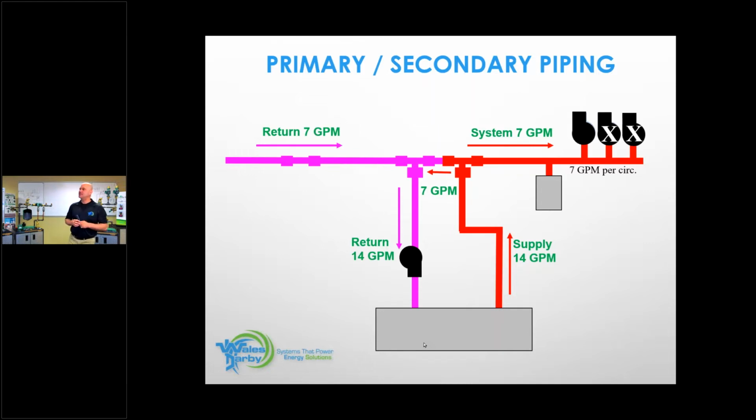What do you got? We got the capacity's gonna ramp down. Okay, great answer. Why will it ramp down? Because we're taking, and I'm gonna use a crazy number here, I know I said condensing boiler, but everybody's comfortable with 160, 180. I have 180 degree water, 7 gallons of it. It's gonna come backwards. I'm gonna call this 160. They're gonna mix and they're gonna drop back into the boiler at potentially 170 degrees.